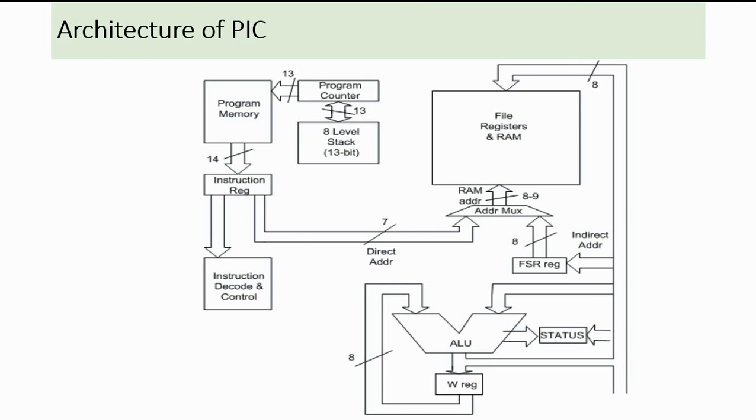In other microcontrollers, the accumulator is placed at the output of the ALU, so the result of the ALU is always stored into the accumulator. However, in PIC microcontrollers, we can store the result either in the W register or in any other register of the data memory.